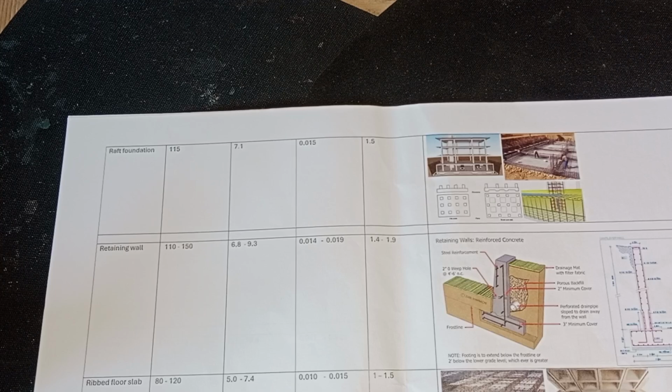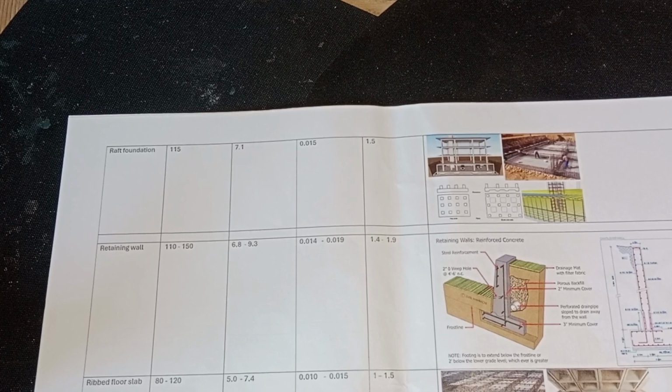Retaining walls are the next. In your retaining wall, you know that here we will have long horizontal and vertical reinforcement always on both sides. Even if the load is not big, we definitely need it for shrinkage and supporting the concrete. And in this case, we will have 110 to 115 kilograms of reinforcement per cubic meter volume of concrete, and 1.4 to 1.9% of the volume in 1 cubic meter is the most optimized.